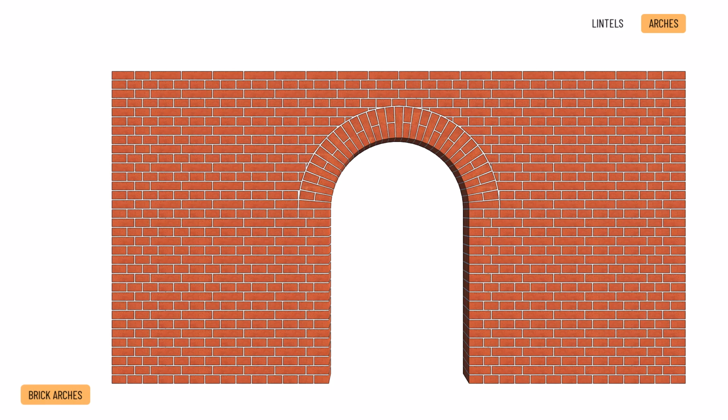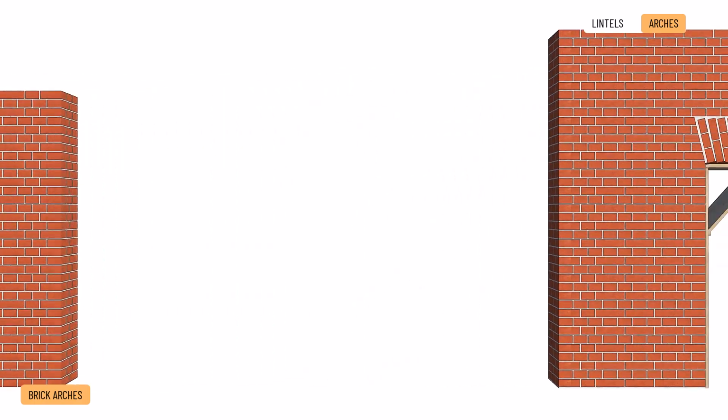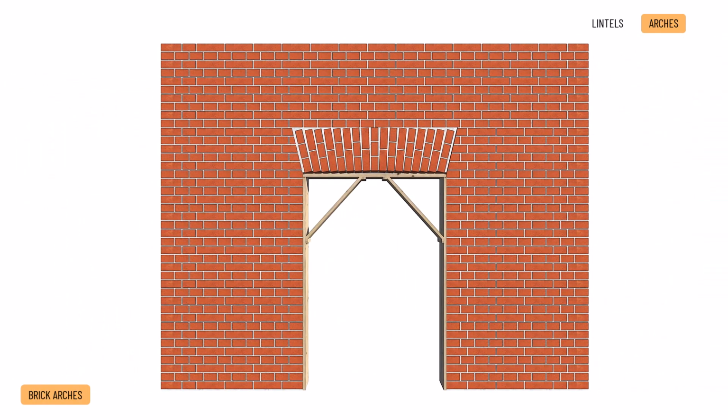While a semicircular arch, or round arch, can span 6 to 8 meters, the maximum span with a straight arch is only around 1.40 meters. The flat arch should be slightly curved with a rise of 2 to 4 centimeters to allow the structure to settle. Boards or planks should support the arch during construction.